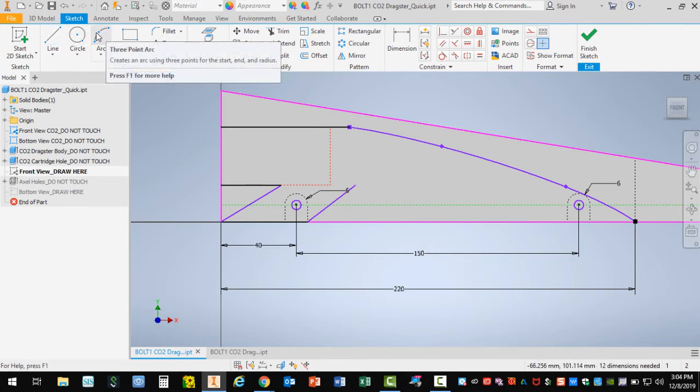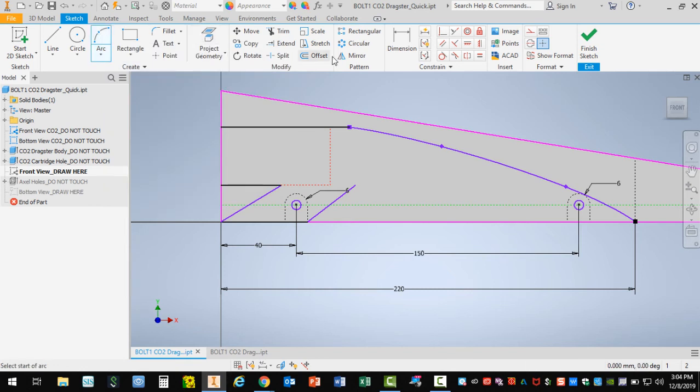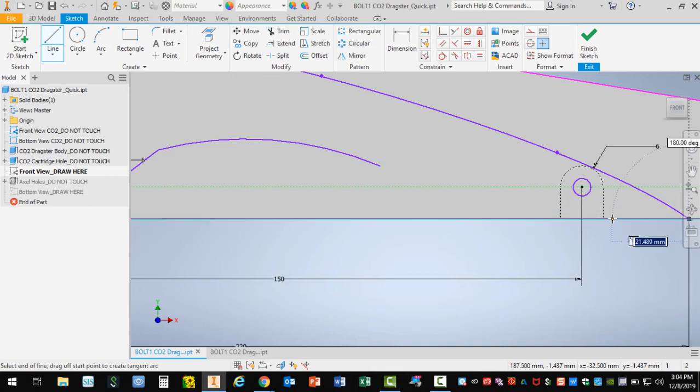Now the default is what's called a 3-point arc. 3-point arc works like so. You click on your start point, you then find an end point. The third click is what bends the shape of the arc. So I'm going to make a nice smooth contour, just like that. Once again, line tool, I can click on the front of my car, I can come back. Once again, same rule applies.